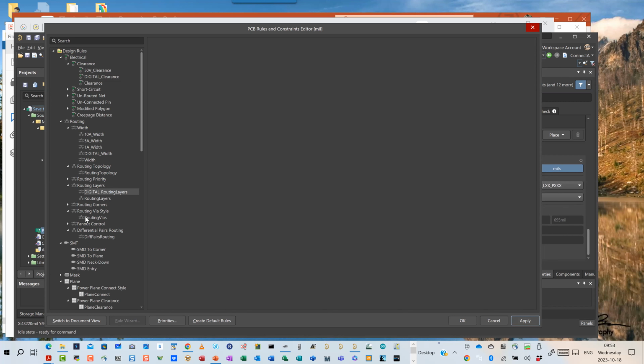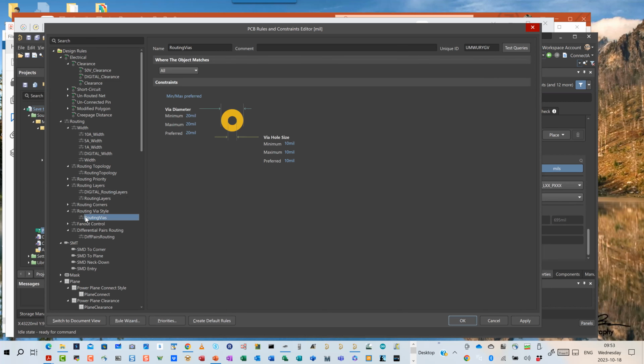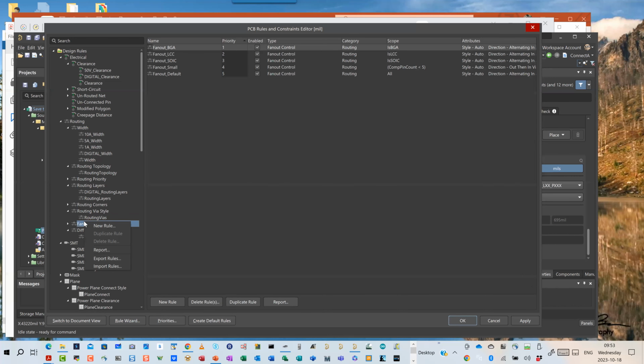Next, we're going to do the routing vias. In the same way, again, I'm going to make the assumption here for those people coming back from PCB1, we went through how to size the plated through holes. For those new in PCB2, what we're going to say is that we're going to want a 10:1 aspect ratio as our minimum aspect ratio with a 10 mil minimum mechanical drill size and 20 mils over the hole size to be our pad size, and so on.